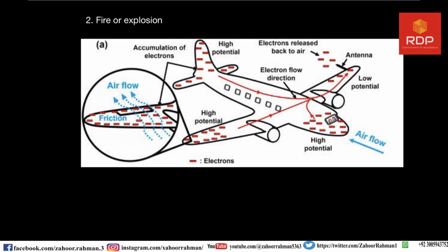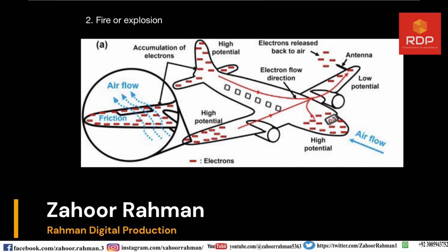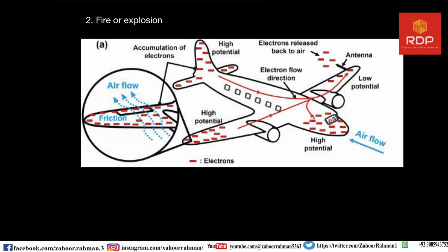Through that touching, those dangling rods are used to shift the electrons, which are produced due to the friction of air with the body of the truck, to the earth's surface, minimizing the potential damage to the flammable oil inside those trucks and tankers.